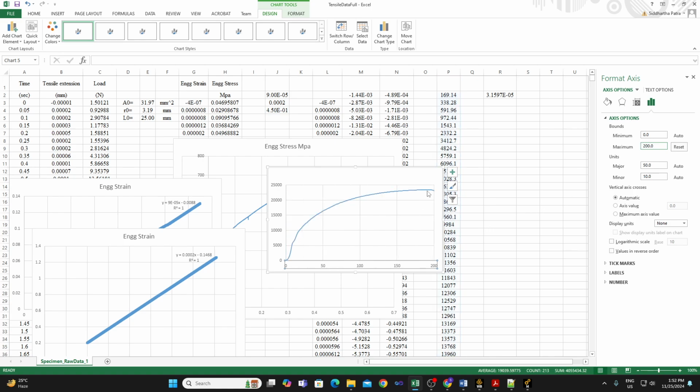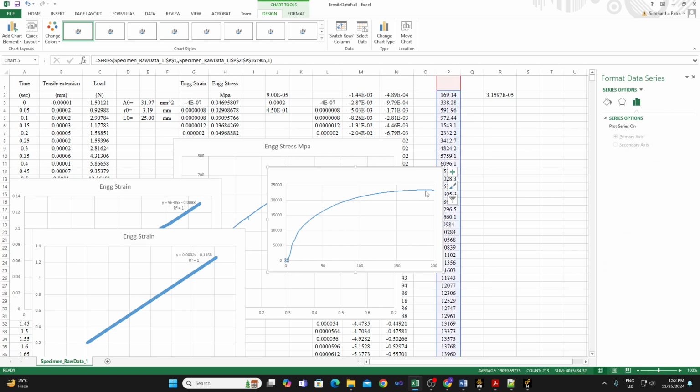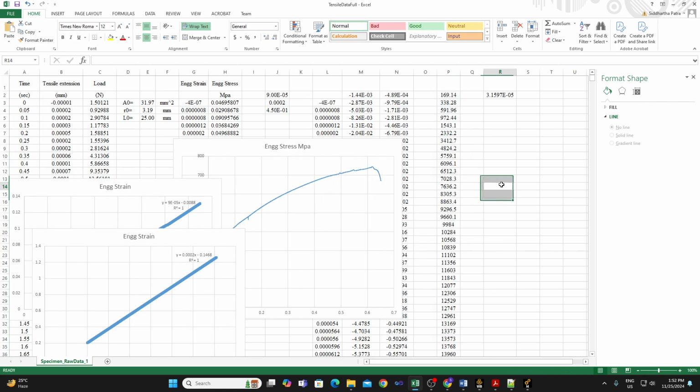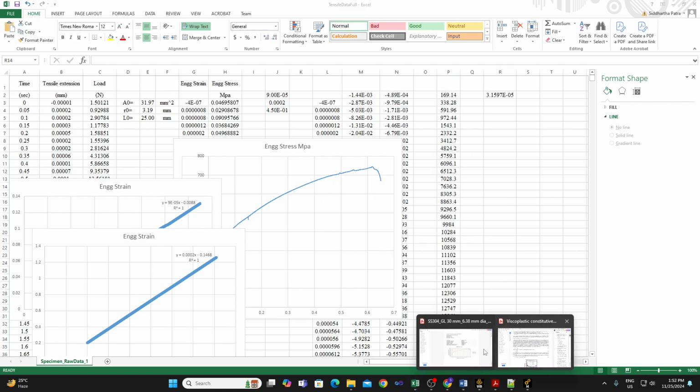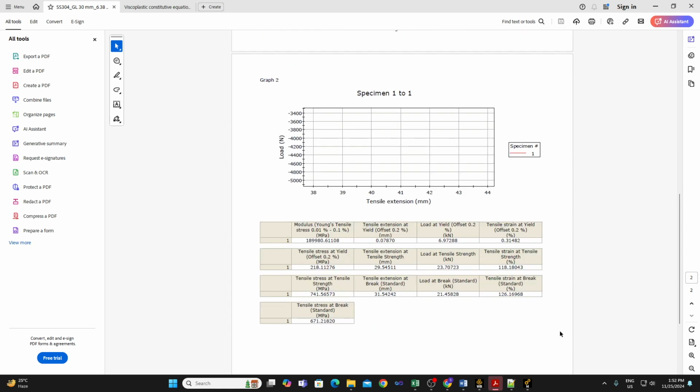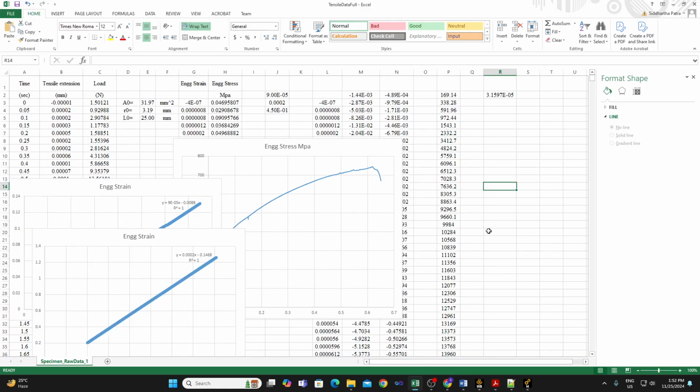Okay, so the maximum force value has gone close to 22 or 23 megapascal. Sorry, 22 or 23 kilonewton. So this is 20 kilonewton, and that is around 23 kilonewton is where the maximum force value has gone. Experimentally, what we had obtained for the load, the tensile strength, was 23 kilonewton. Of course the diameter was bigger, so there would be some deviation, but you see the load order is nearly the same.